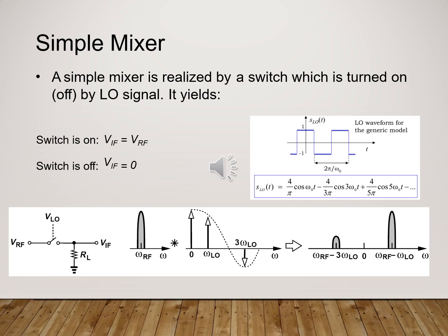But to recall, why do we convert RF to intermediate frequency? There are several reasons. The main reason is that the bandwidth of a filter is proportional to its center frequency. In receivers where the filtering is done at the incoming RF frequency, as the receiver is tuned to a higher frequency, its bandwidth increases. So the main reason for using an intermediate frequency is to improve frequency selectivity.